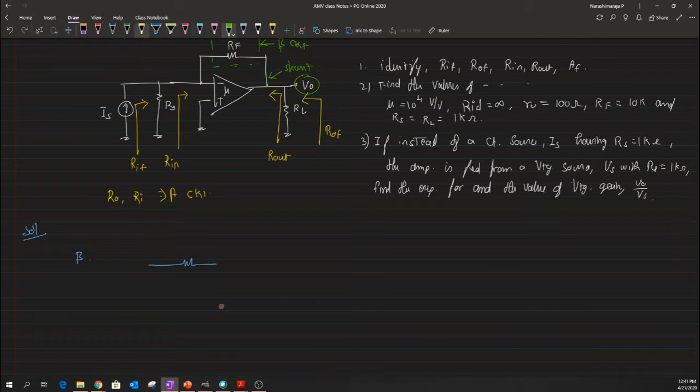Okay, and what has been mixed at the input is basically a current. So here what we are trying to mix is a feedback current, and the feedback current has to move up. And the value of Is would then come over here, and there is a reduction in the value of this current Ii. Now clearly you could see that this particular point where we are feeding the signal as well as trying to feed the beta network's terminal actually gives us a notion that it is going to have a current mixing. So that is how one could quickly end up having a result for it.